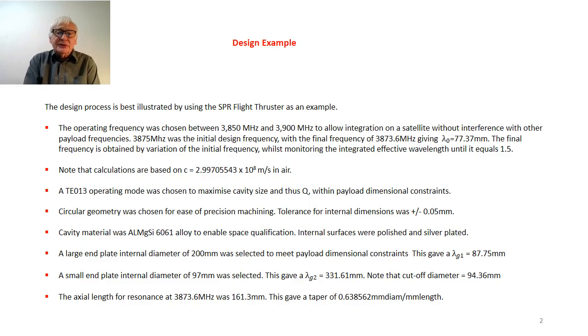Circular geometry was chosen, again for ease of machining, and we specified the tolerance for the internal dimensions of plus or minus 0.05 millimeters, plus or minus 50 microns.